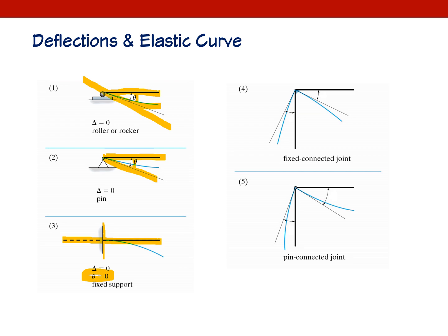Alright, and we have discussed the difference between rigid connection and fixed connection many times, but still the textbook says fixed connected joint. That is not the correct term. This must be rigid connection. A fixed connection will not rotate, but a rigid connection will rotate. But the rotational angle will be the same in any rigid connection.